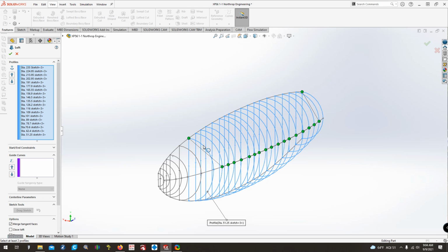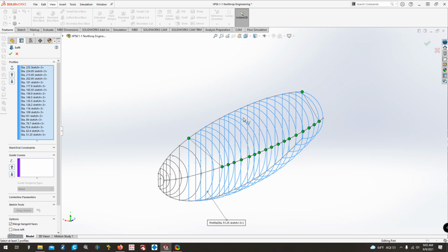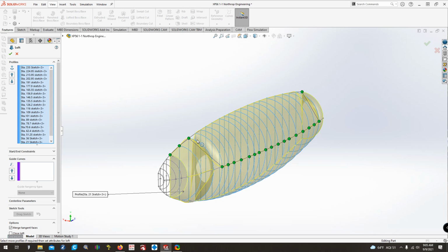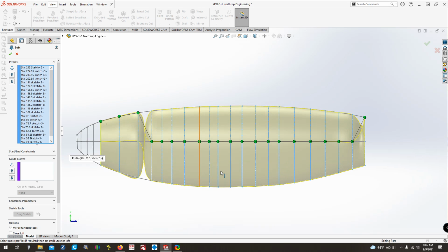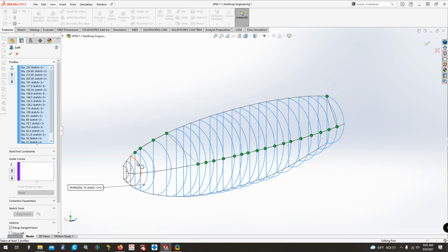And then eventually you see, hey, I selected that profile and the yellow went away. Does that mean it's going to fail? Not necessarily. It just means that your preview is probably not working quite right. Like you can see here, when you click on it, it's got this weird dip. So just keep selecting your profile. So here we go. See, now it's got this really weird looking shape, like it twists on itself in a couple of places. So don't worry about that just yet. So again, just keep selecting all of your profiles.